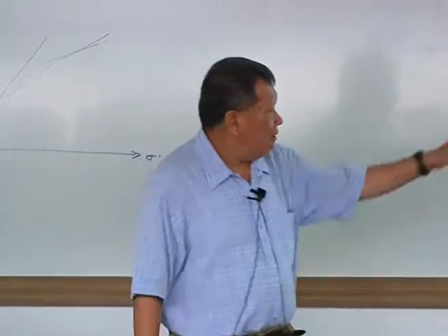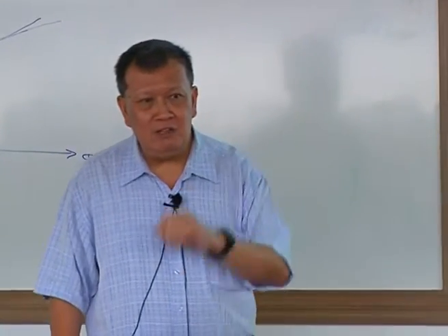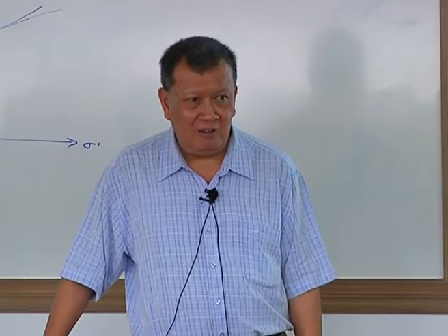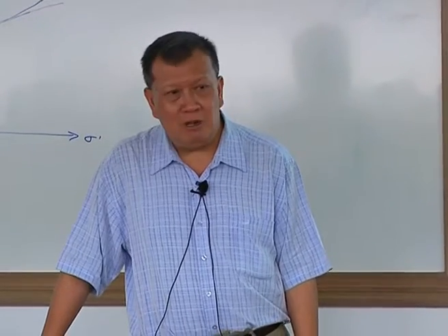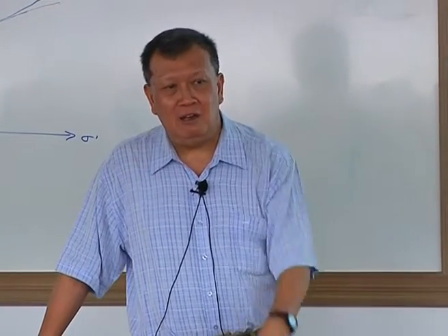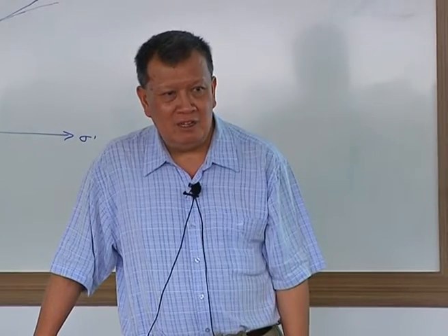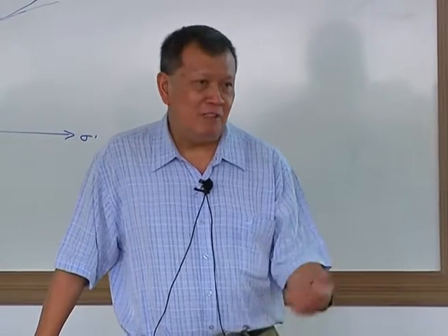If it is just apparent cohesion like this, you put it under zero effective stress condition, there will be no strength. It will just disperse. The moment the negative pore pressure dissipates, end of the story. Okay? So the best thing you can do is to just immerse it in the water, wait for 7 days or 2 weeks, come back, take a look, see what happens.